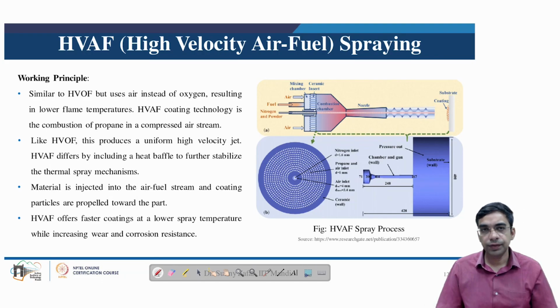Like HVOF, HVAF differs by including a heat baffle to further stabilize the thermal spray mechanism. The material is injected into the air fuel stream, and the coating particles are propelled towards the component. HVAF offers faster coating at lower spray temperature while increasing the corrosion and wear resistance.